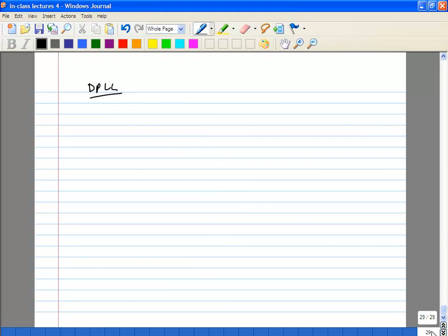Okay, so finally we will just devote a quick page to the DPLL, the digital PLL. The basic idea is, your normal PLL consists of PFD, charge pump, loop filter and so on. You are converting an input phase difference into a pulse width, and then that pulse width into a current with a variable pulse, so effectively into charge, which goes into a loop filter. The loop filter filters out high frequency components, and you feed a DC voltage to the VCO. In the case of the DPLL, you want to make completely digital blocks. So it looks like this.